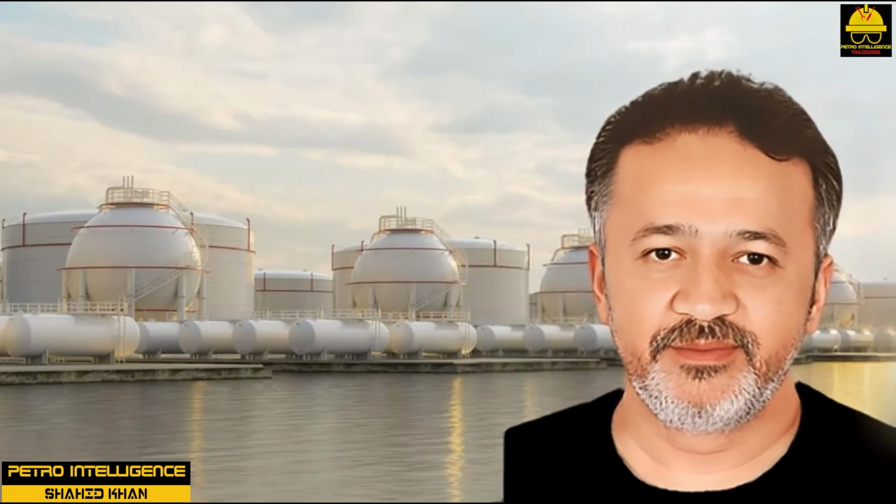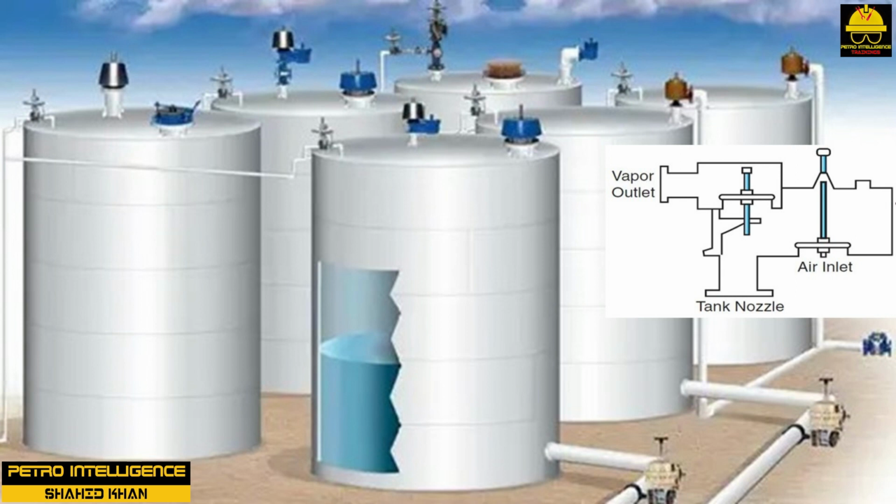Conservation vents. Fixed roof tanks that store volatile fluids are often equipped with a conservation vent as shown in the picture. A typical conservation vent is equipped with two valves having weighted discs to regulate pressure during operation. The exhaust valve will not open until a slight positive pressure is reached in the tank, and the intake valve will not open until the tank is under a slight vacuum. Controlling the pressure in the tank reduces loss of vapors.